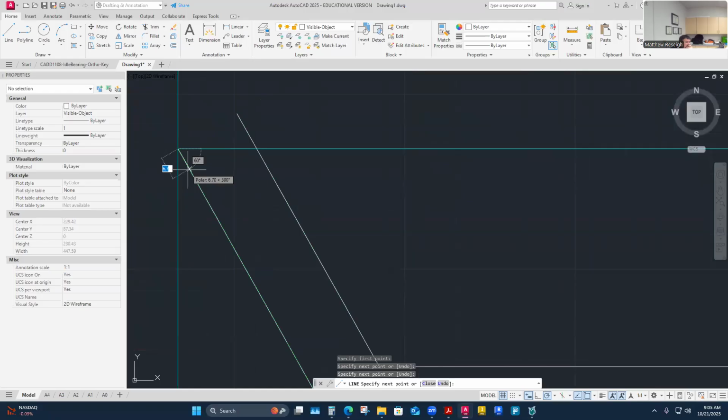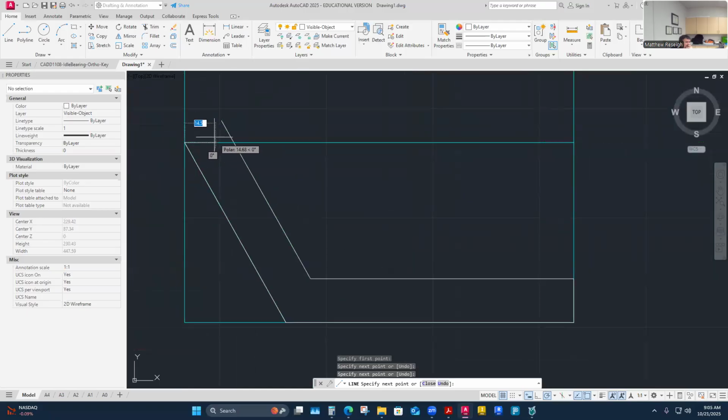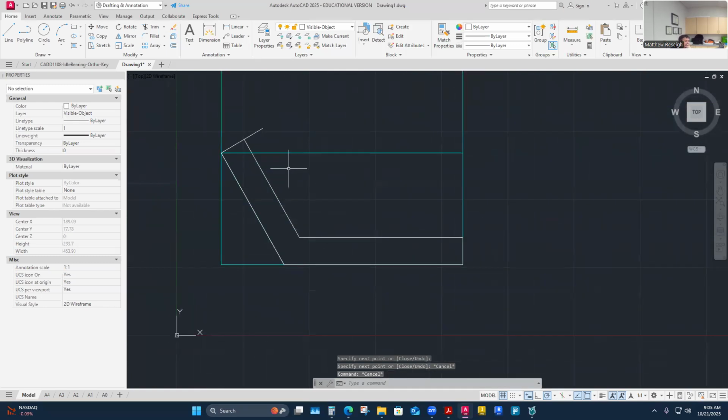My boundary box is a little bit misleading because you might think it has to stay in there, but it doesn't. So I'm going to draw this one perpendicular now. I'll just leave it long. It's actually perpendicular, a 90-degree corner here, right across the top here. So that's 30 degrees is also what I'm seeing show up. I'm just clicking it long here. I'll trim it off, but that's technically the boundary of this, and that's based off of this. I'm keeping this at 95 millimeters for sure. So it's breaking the boundary like this, which it should.